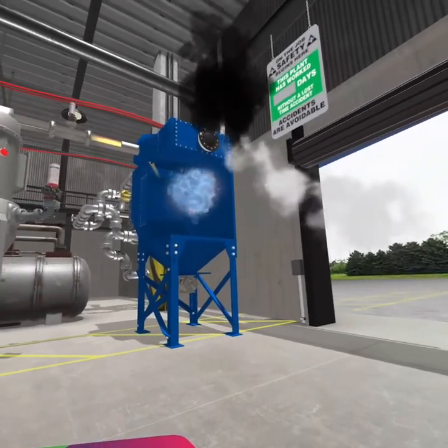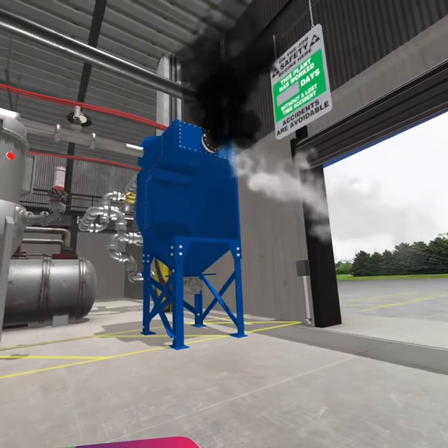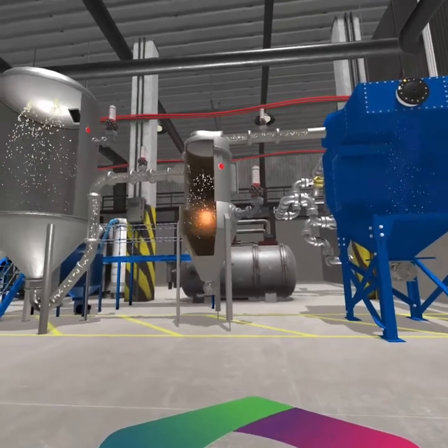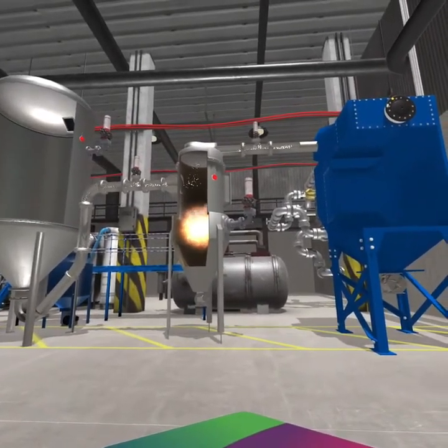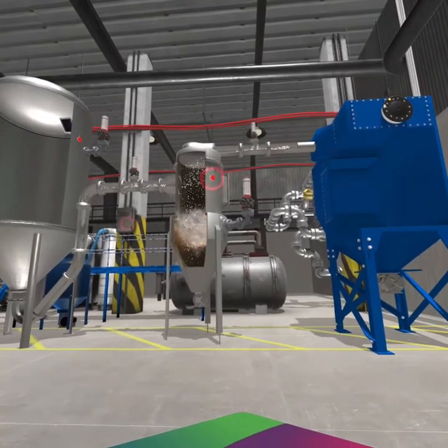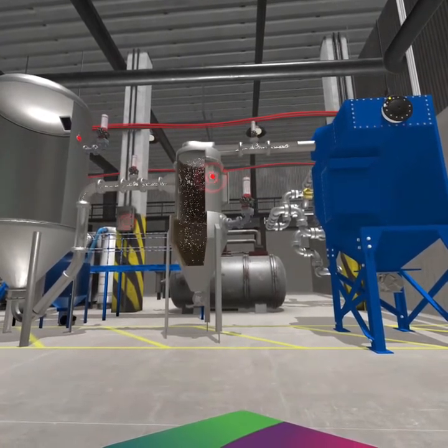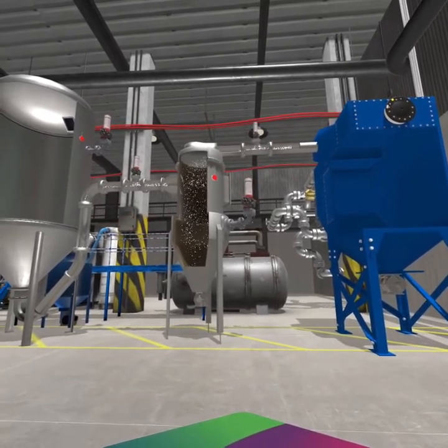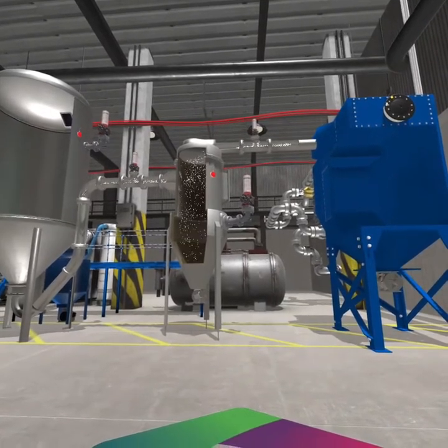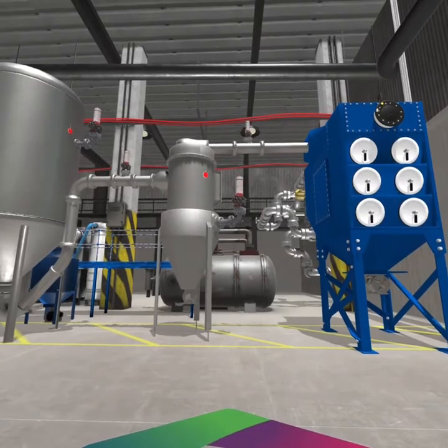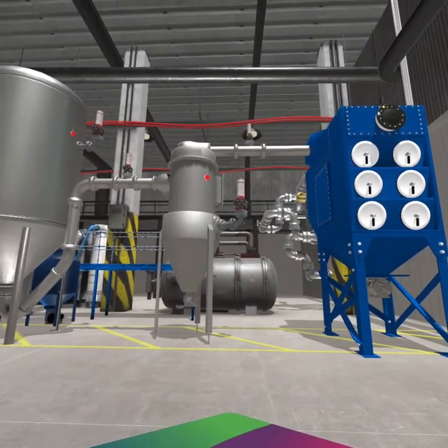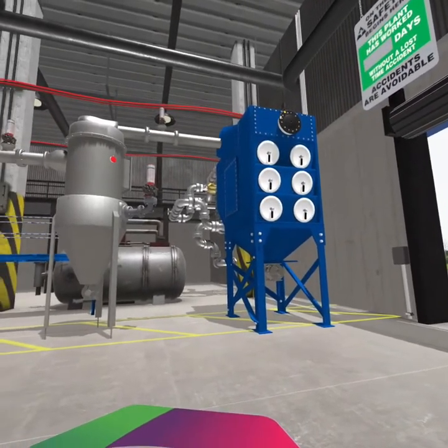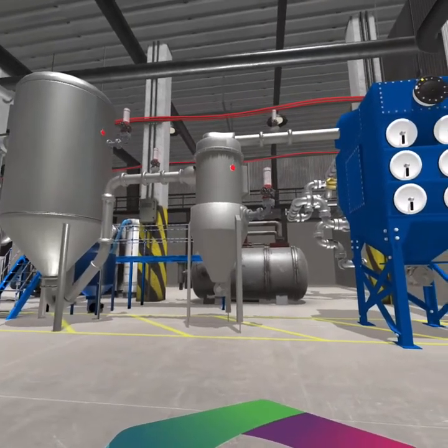But what if the ignition source finds the perfect conditions for an explosion in a different vessel? Let's take a look at an explosion which occurs in the cyclone. The smart DS intelligent pressure sensor detects the pressure wave at the earliest stage and then communicates this to our control panel. Within milliseconds, the controller actuates the high-speed suppressors. They deliver a suppressant which stops the combustion process before critical pressure levels are reached. As you can see, the IEP suppression system coupled with isolation devices worked together to stop the explosion in its tracks.